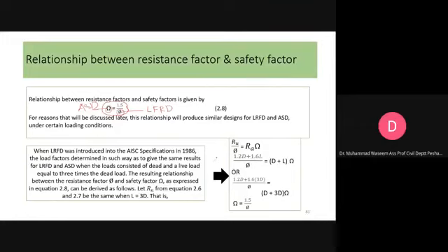Okay, and how do we proceed with the derivation? You will start with this one. We know that this is R, the nominal strength. You can calculate the nominal strength in LRFD, and you calculate the nominal strength in ASD. So basically you equate them together. You put the value of Ru for a case of dead load and live load only.